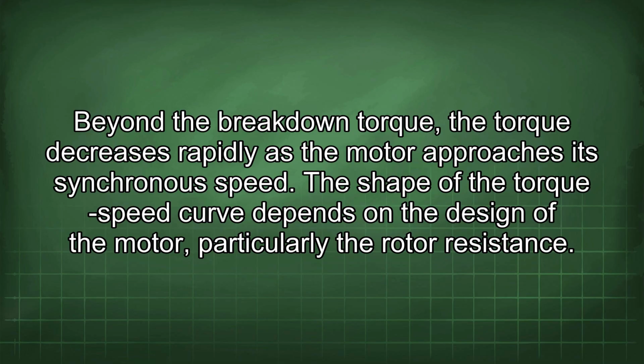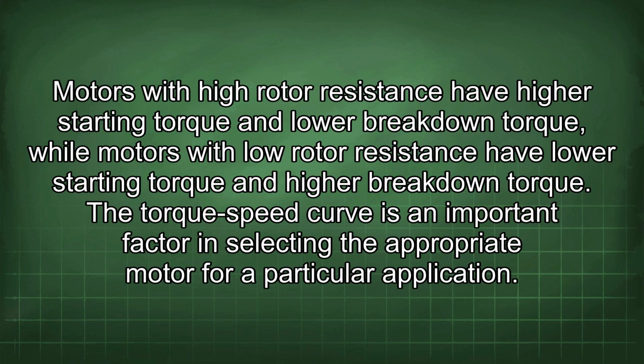The shape of the torque speed curve depends on the design of the motor, particularly the rotor resistance. Motors with high rotor resistance have higher starting torque and low breakdown torque, while motors with low rotor resistance have lower starting torque and higher breakdown torque.